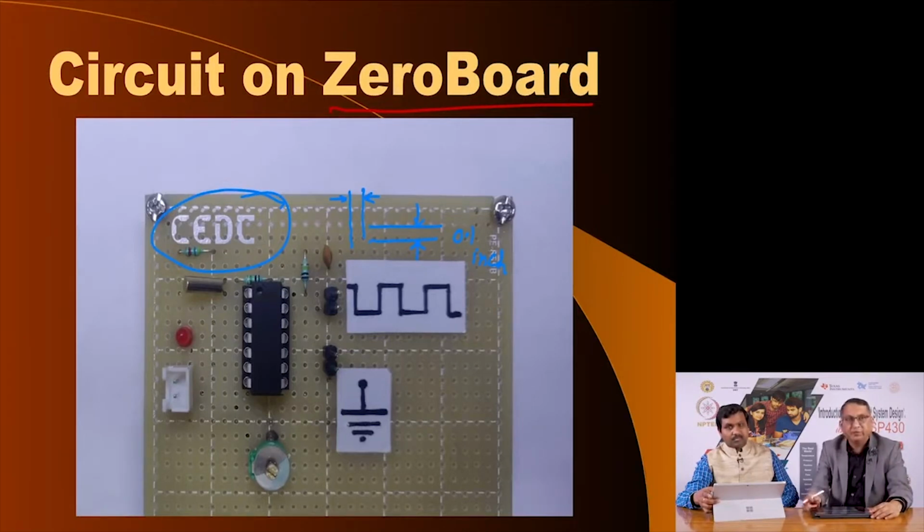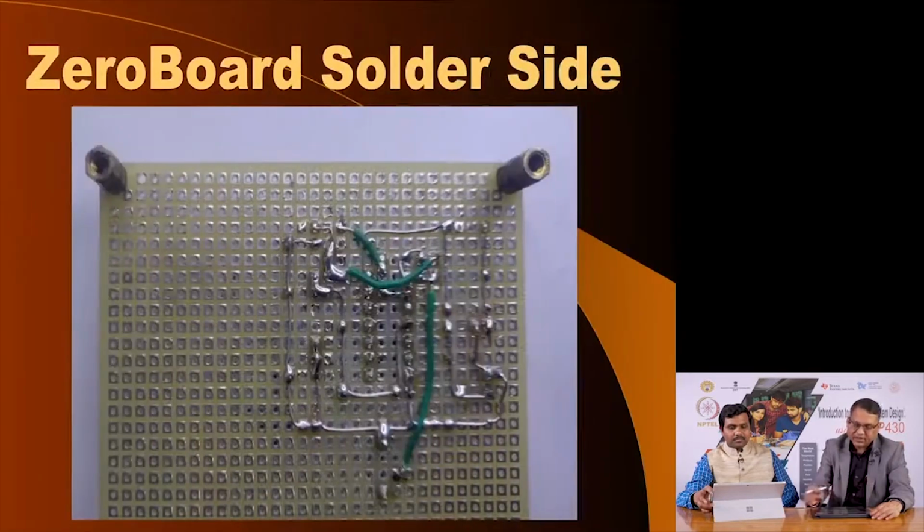The material of the PCB is very important. This is called FR4, which stands for fire resistant type 4 substrate, that is the insulating material on which copper tracks or copper pads in this case are pasted. You can insert components from this side and they are soldered on the other side. So, this is the top side of the zero board or general purpose board. In the next slide you see the bottom side of the same circuit.